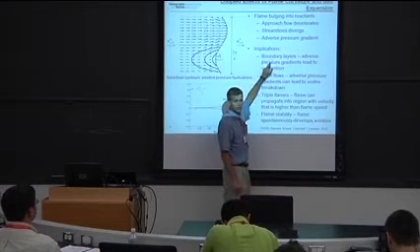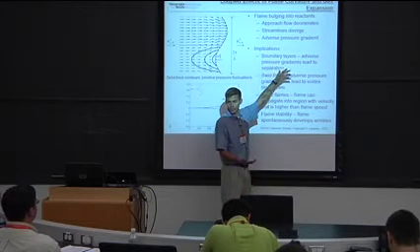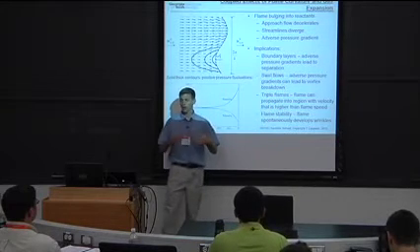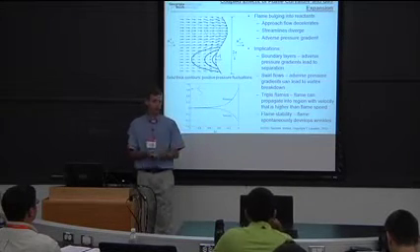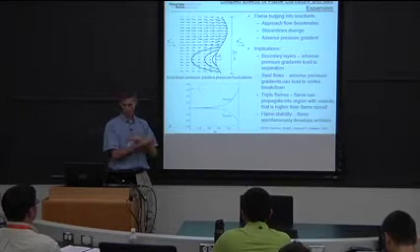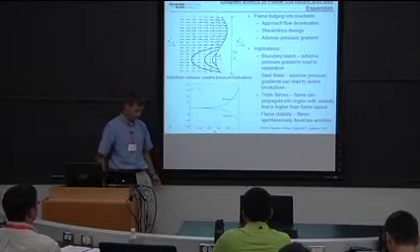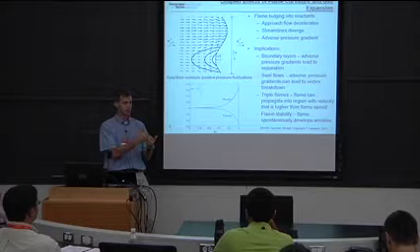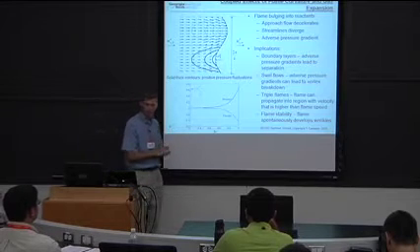Well, all right, now suppose this flame is in the boundary layer. Well, what do you know about boundary layers? Boundary layers don't like adverse pressure gradients, do they? What happens when a boundary layer sees an adverse pressure gradient? It can cause the boundary layer to separate, right? So flames can make your boundary layer separate. A flow which is very happy, a straight pipe where the flow is very happy, having a nice boundary layer, will actually detach, separate, and you'll have a reverse flow region.